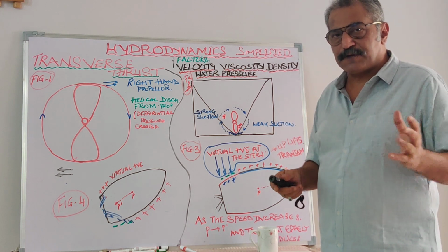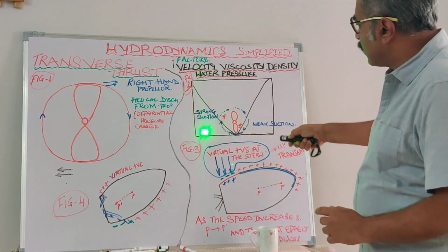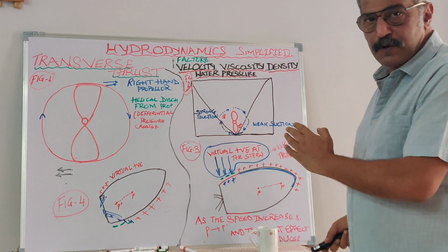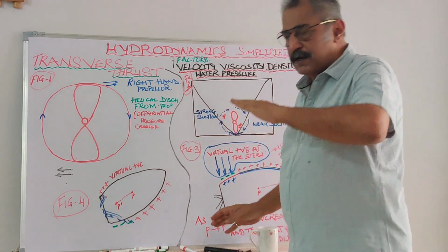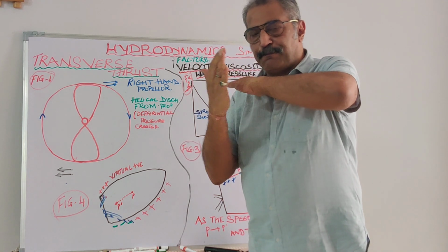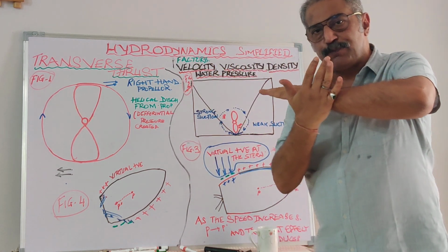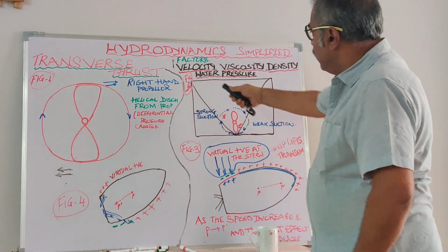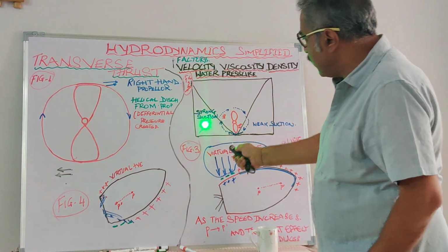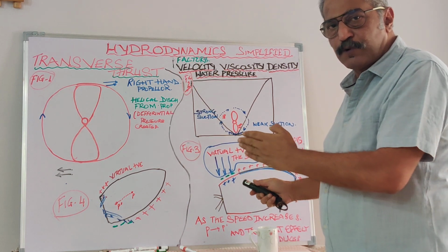On the port side, there is a certain amount of suction created, by virtue of which the water is flooding in onto the port quarter. On the port quarter, the water is getting flooded in for the water which is displaced because of the right hand screw. So what happens? On a vessel with a right hand screw propeller churning clockwise going ahead, there is a push given here on the port quarter by virtue of which the bow cants to port. In other words, this is the ship I've drawn here, looking at it from aft. If I give a push here, the bow will start canting to port, or the bow will start turning to port.